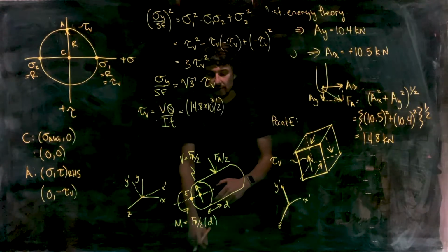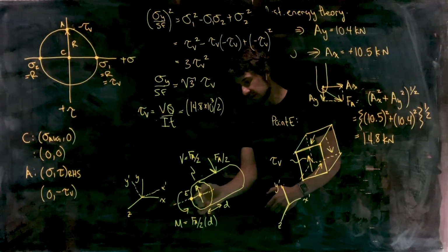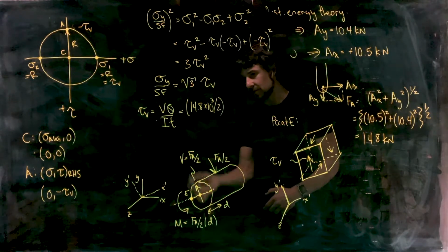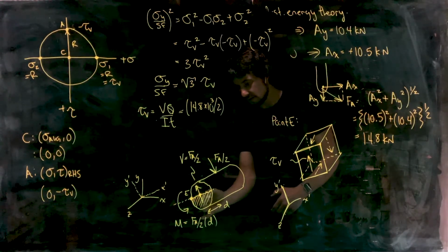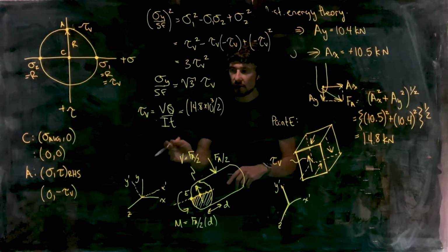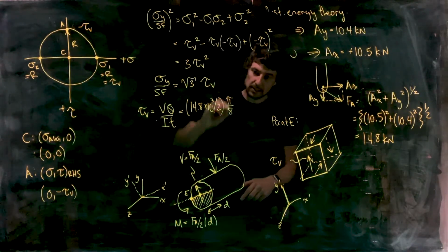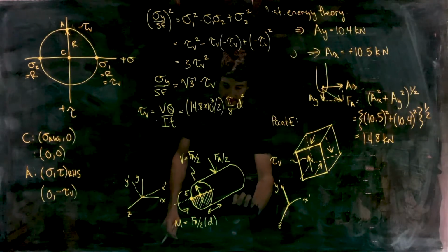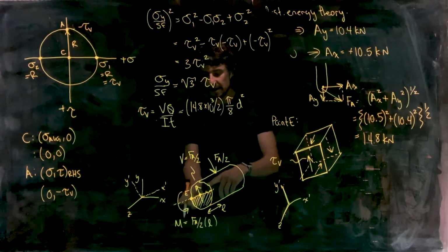And then Q, we want A prime, Y bar prime. So we're calculating the shear stress at point E, which is the shear stress shared by all points along the centroidal axis, or the axis that passes through point E and is perpendicular to our shear force. So for our area A prime for Q, we choose the portion of the cross section above or below that line that we're calculating the shear stress along. So that area right there. So that area is going to be what? Pi over 4 d squared for area of a circle. So we've got pi over 8 d squared there, recognizing that the d is not that d down there. Let's just change that to L so we're not confused. This d is the diameter of the pin.